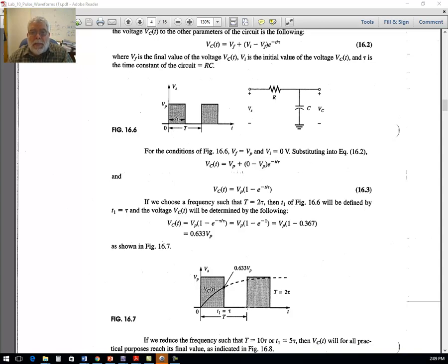They're supposed to be equally timed, the same duration each, the pulse and the zero. In this case we call it a duty cycle of 50%. So 50% of the cycle the pulse remains high, and 50% it remains low.